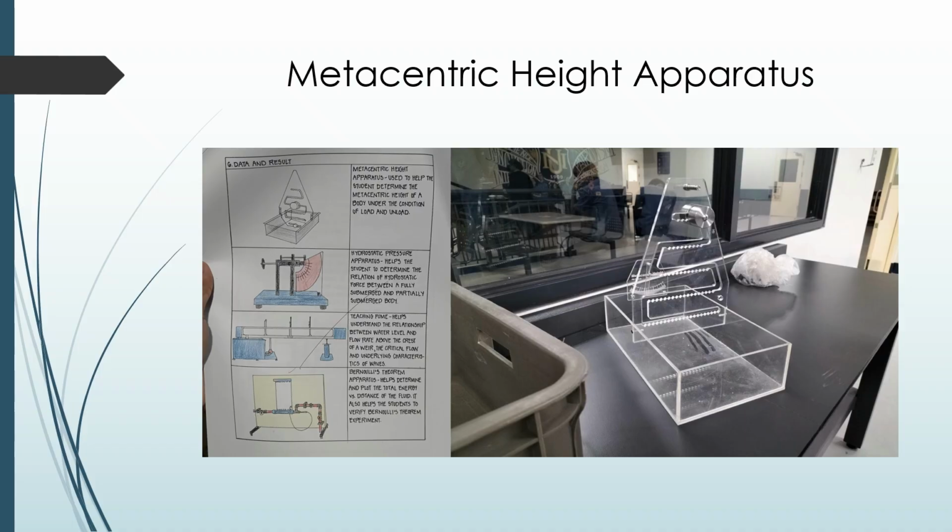Through this apparatus, students can observe how the position of the center of gravity affects the equilibrium of the floating body. By adding or removing weights and recording the resulting angles of tilt, they can calculate the metacentric height and analyze the stability behavior in different loading conditions.